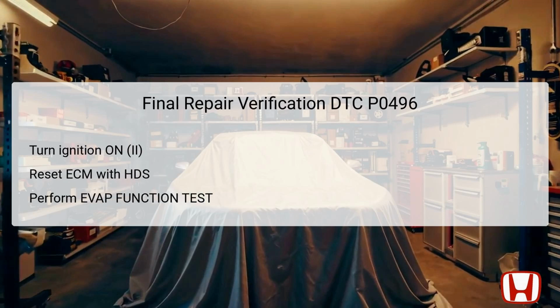Final repair verification is crucial to ensure that all steps taken have effectively addressed DTC P0496. First, turn the ignition switch to the on position to power the necessary systems. Then use the HDS to reset the ECM, ensuring that it is cleared of old codes and is ready to read current operation data accurately.